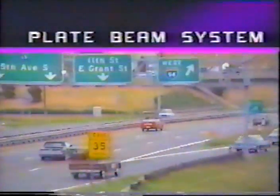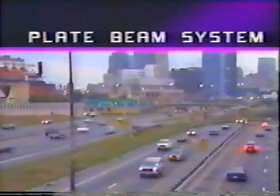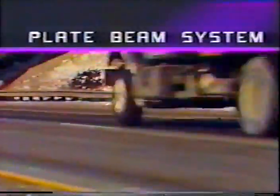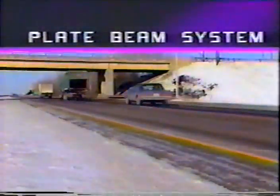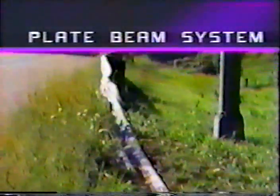In contrast, the plate beam system is primarily used to protect vehicles and passengers in high-volume urban areas from obstacles which are greater in number and closer to the road, or in high-hazard areas such as approaches to bridge abutments. Because its rigidity controls the amount of deflection, the plate beam system is also used because it can still function after impact. Each of these two systems has design elements which are crucial to the goal of safely redirecting a car and its passengers.